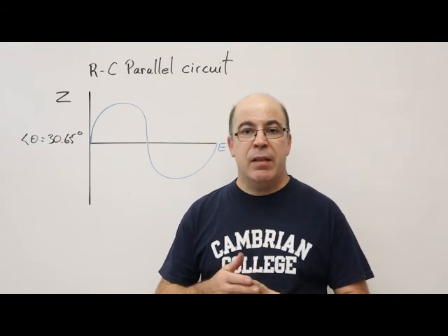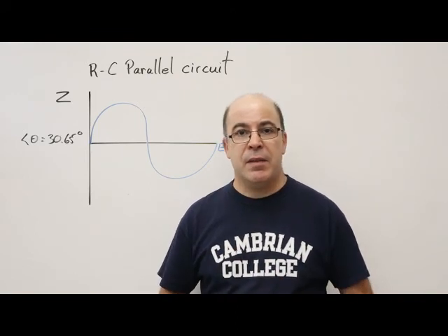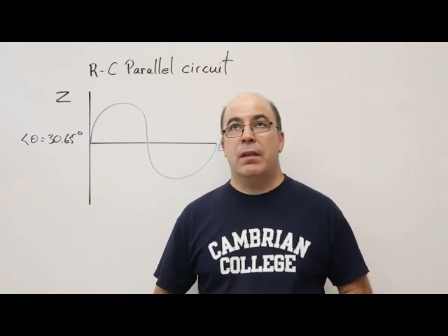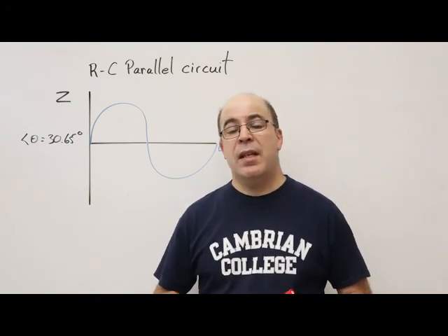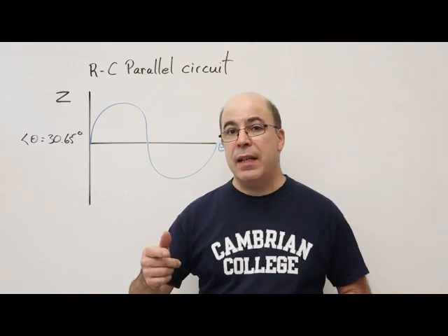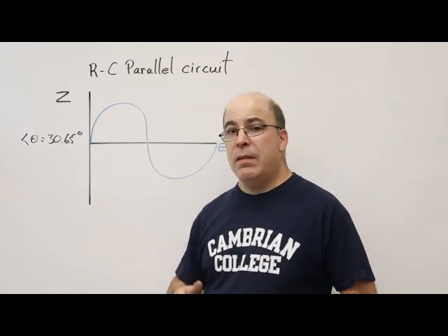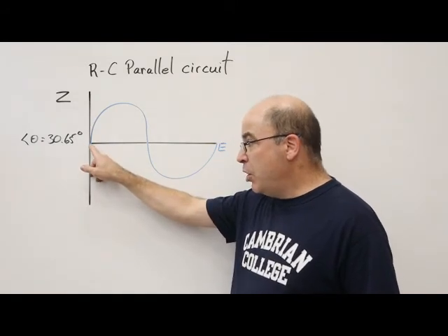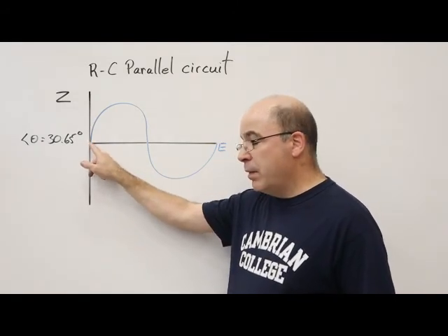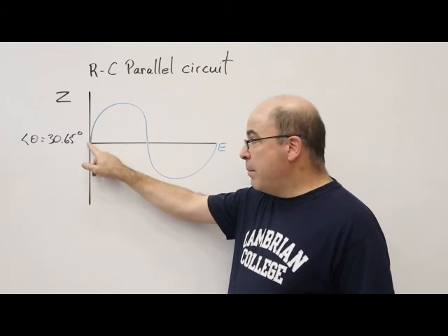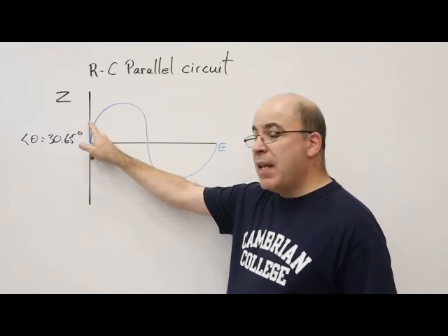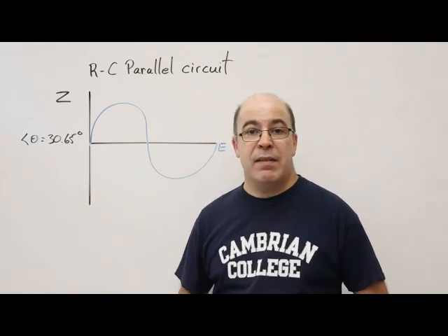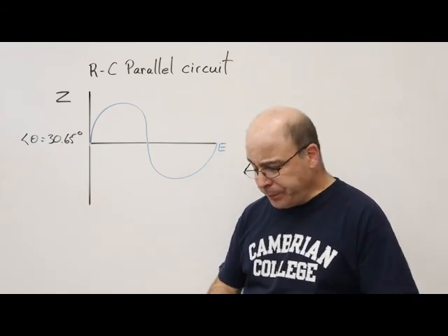And that means then, and we've seen this in certain textbooks, they'll make the statement that capacitors oppose a change of voltage and that current will be leading. This case is true. When the voltage waveform is at the 0 point here, that means that my current is actually going to be in the positive alternation. It'll be leading by that 30.65 degrees.